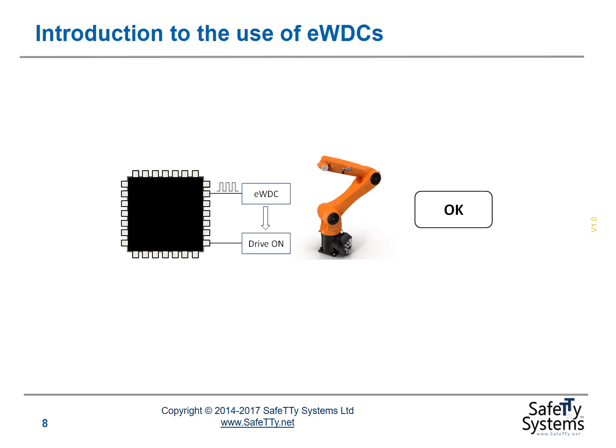Let's modify the design a little. Now we add an external watchdog controller to the system. So now the watchdog controller is also responsible for ensuring that the drive circuitry to our robot is enabled. And the watchdog controller is, we assume, controlled by a pulse stream that comes from our microcontroller. If we don't generate a pulse stream from the microcontroller, the watchdog controller is not enabled and will have no power to the drive. So under these circumstances, everything is okay.